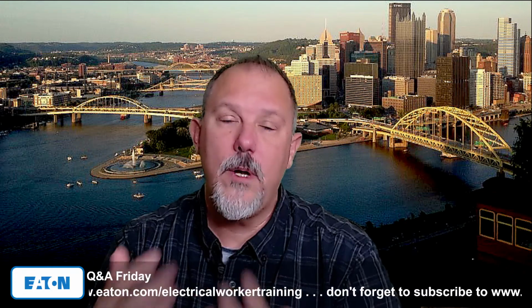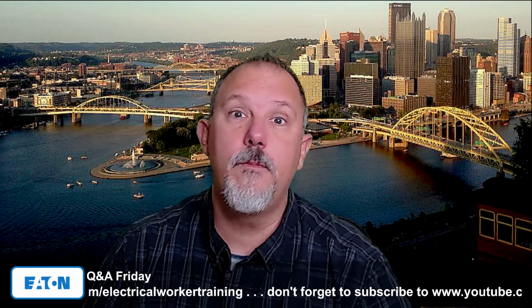So if I can avoid taking dead fronts off and exposing energized bus, where I have to calculate the arc flash boundary and all that jazz, that person might have to really technically be dressed for the occasion, depending upon the condition of maintenance and everything else that's going on. Do I want to take that effort? Even if you say, look, he's going to take the dead front off, take the picture and put the dead front back on again.